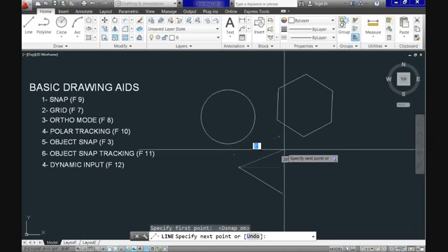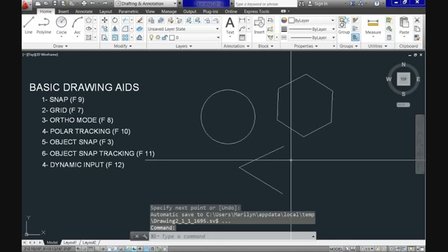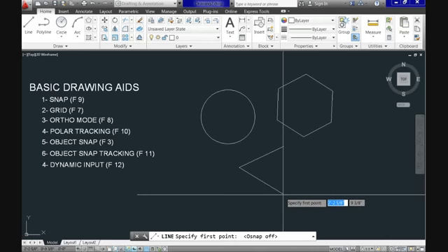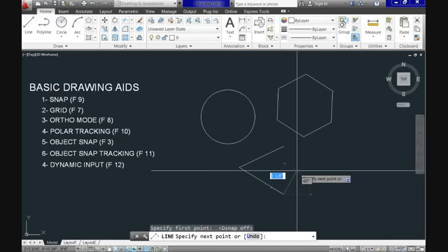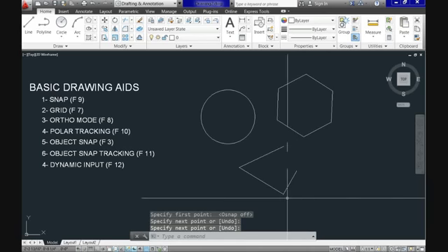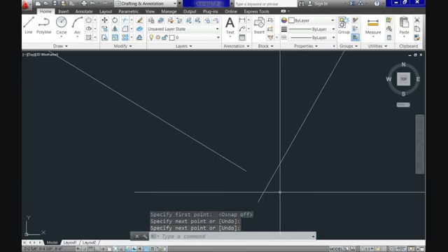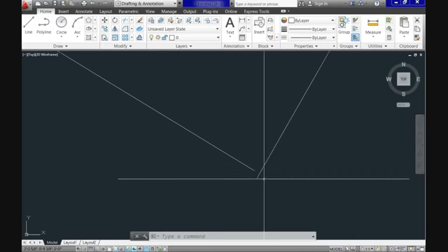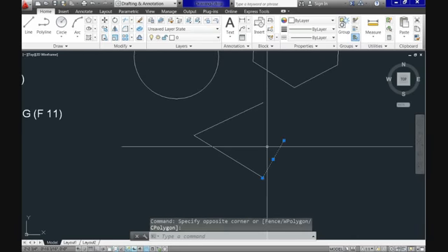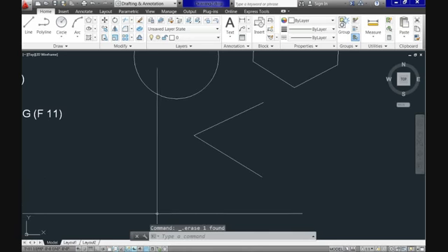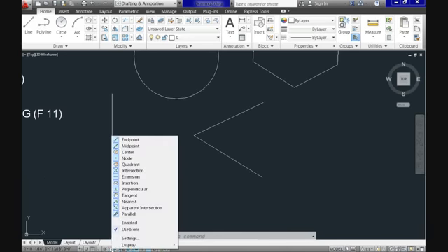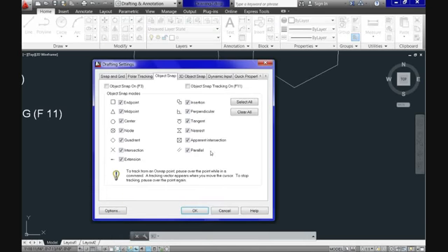When you use the suggested points, you get a perfect connection. In this example, you can see what we're talking about. I'm drawing a line here which seems to be connected to this one also. Now, since I'm doing it based on appearance, after it's done, I zoom in really close just to discover that these lines are in fact separated, not connected at all. So if my intention was to connect both lines, I should use one of the suggestions of object snap.